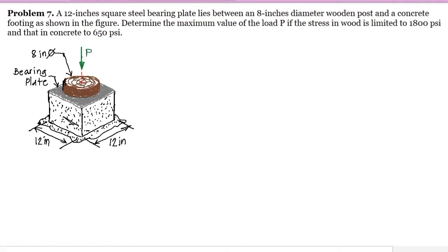So makikita natin dito, given in our problem, that we have here an 8 inches diameter wooden post and we have a concrete footing with a dimension of 12 inches by 12 inches. So given dito yung mga allowable stresses. For the stress in wood, that is limited to 1,800 psi. For stress in concrete, that is limited to 650 psi.